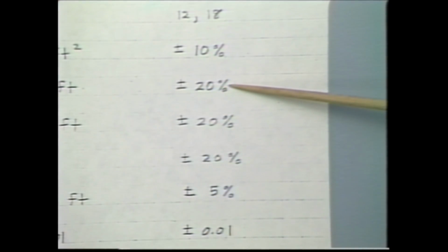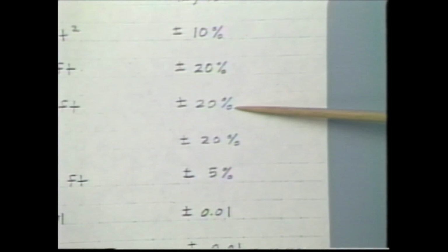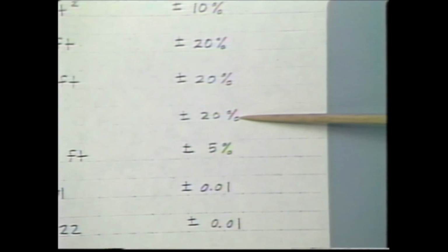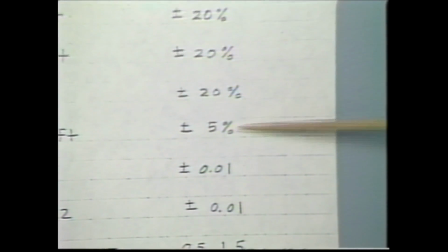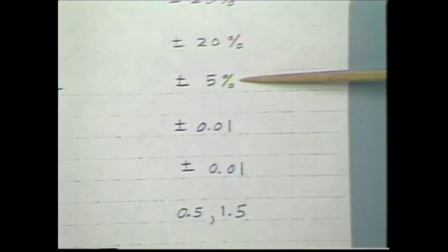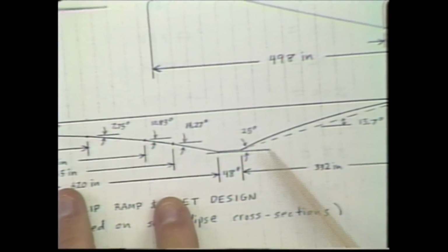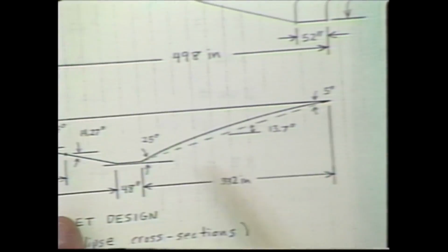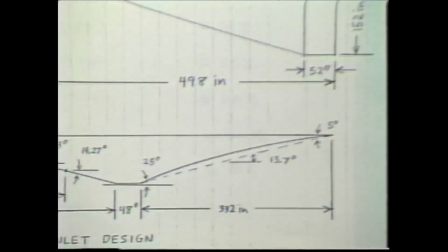Also looked at nozzle height independently, nozzle length, 20% variations, combining the nozzle length and height together so you slide along the chordal angle. The nozzle cowl length, that's right here. That's the cowl of the nozzle. The internal portion of the nozzle is dictated by that cowl. There's our nozzle shape. There's the height and its length, and those are the things that were varied, and again, that chordal angle.